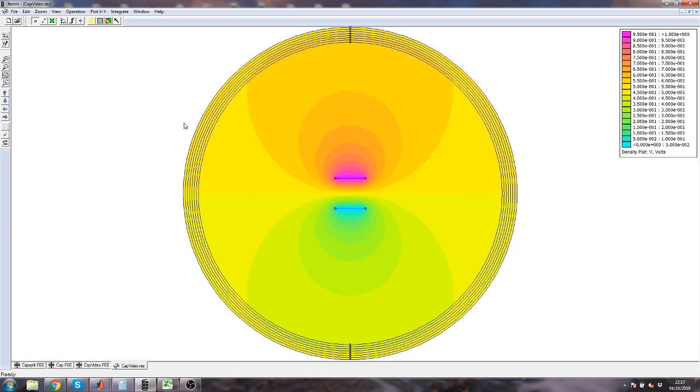And we're looking at a plot of the voltage at each grid point. So around the anode where I prescribe 1 volt, I can see that it's just about a volt, 9.5 times 10 to the minus 1, so that's nearest down at 1. And around the cathode, which I prescribed 0, is pretty much 0 volts. And in between we have this graded region where the voltage is dropping as we pass from one plate towards the other, which is what you'd expect to see.